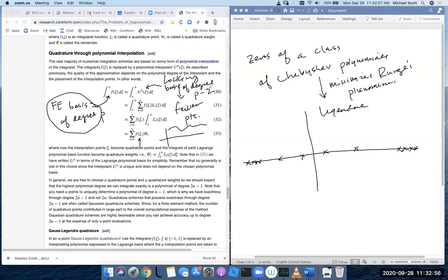Yeah, that's what I'm trying to emphasize here, is that through quadrature, locking says I don't have my finite element spaces quite right, so I'm locking up. So rather than trying to figure out exactly what those spaces are, let me use quadrature to map into spaces that should be better suited for the problem.